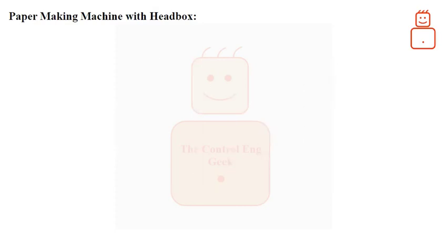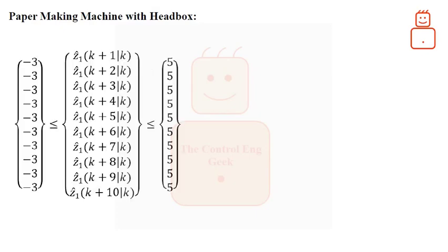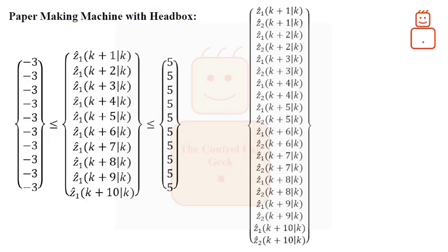Lastly, for the control output constraint, we could write the following along the prediction horizon HP. Note that, as I explained in the previous video, the constraint on the control outputs should be on all involved or considered controlled outputs regardless of whether they are being constrained or not. Thus, the right vector of the control output should be as shown, which is of length 20 by 1.